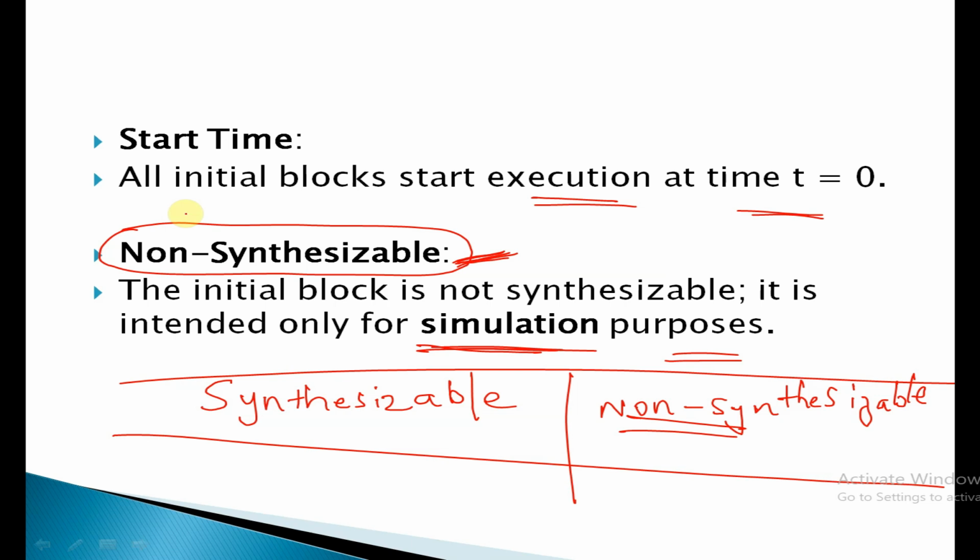If you are writing your code only for testing your particular design, you can use non-synthesizable constructs. But if you are writing your code for implementing it on some hardware, then you should only use synthesizable constructs.